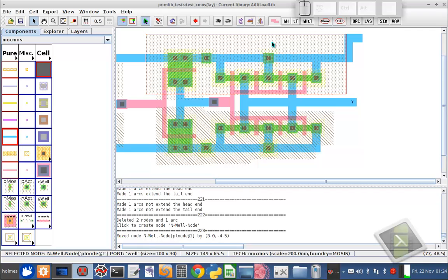When this is exported out to GDS2, all the elements are merged together into one geometry. So this saves a lot of disk space in GDS2. It makes the manufacturing and the pattern generation much easier, and so it's a common practice to do it that way.